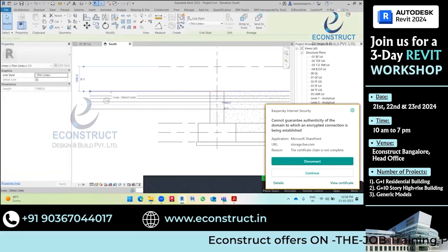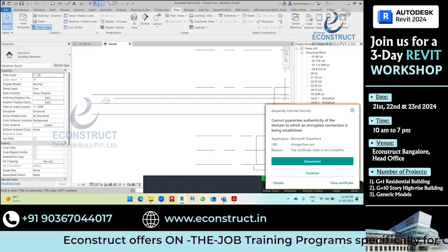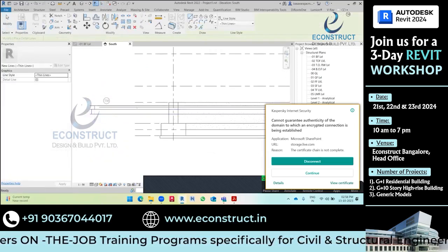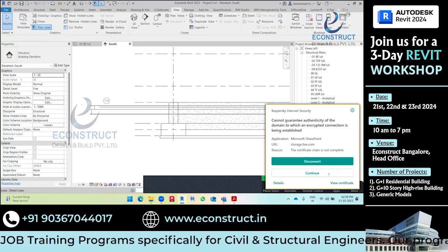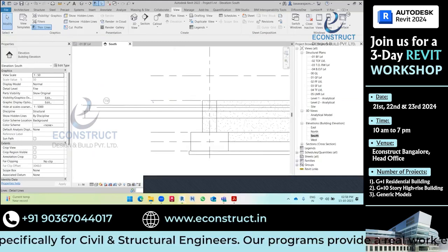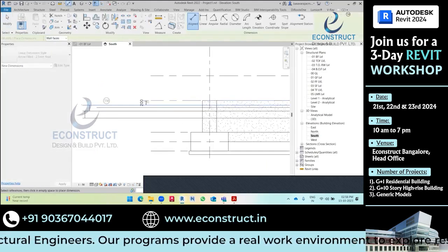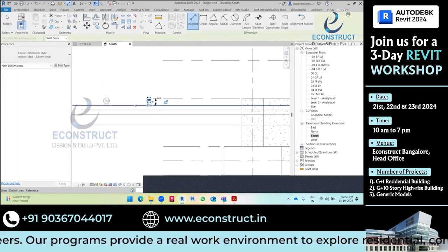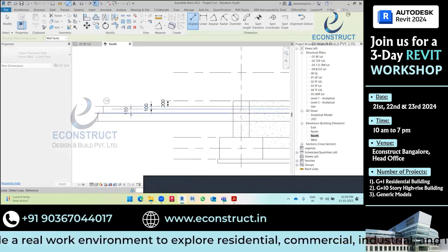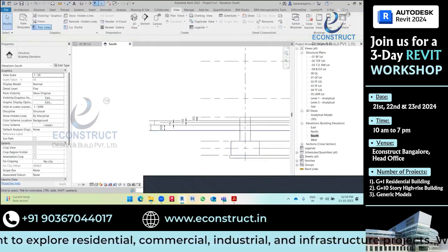Okay. So this is our primary range, and this is our view depth. But our reference level is the basement floor level. So from the basement floor level, we are 200 mm down. This is the top plane, 100 is the cut plane, 150 mm is the bottom plane, and 300 is the view depth. This view range I will set.